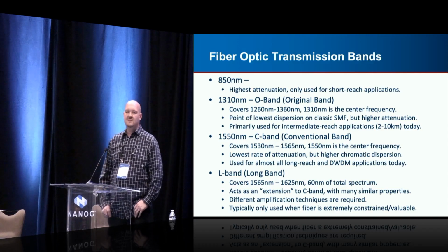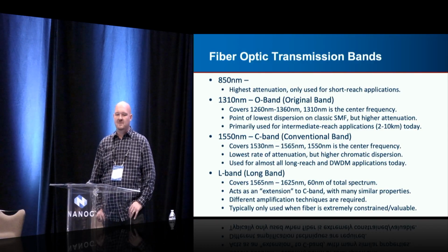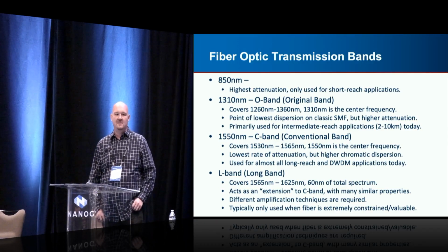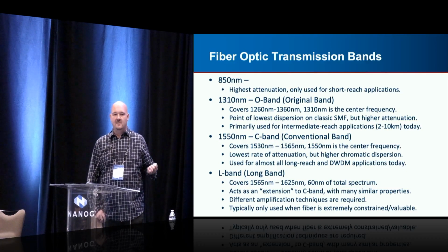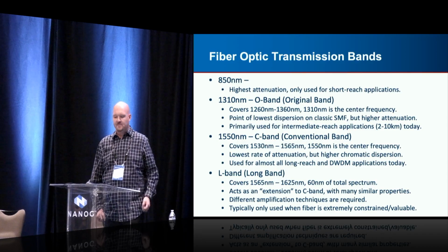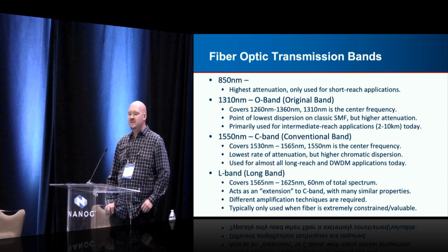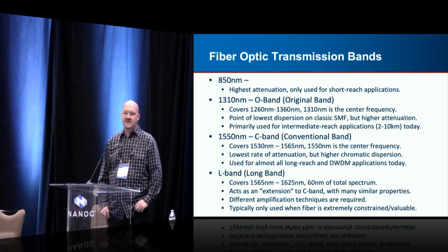You'll see it used for longer. Some people are doing 30, 40 kilometers with 1310, but it's the point of lowest dispersion for classic single mode, but it's also a point of higher attenuation. So that's why you see it used for that intermediate reach.